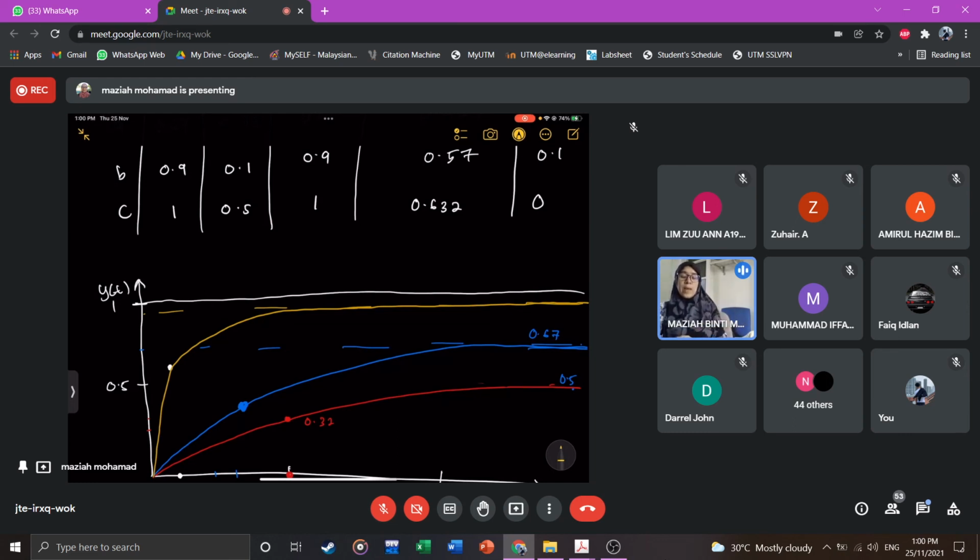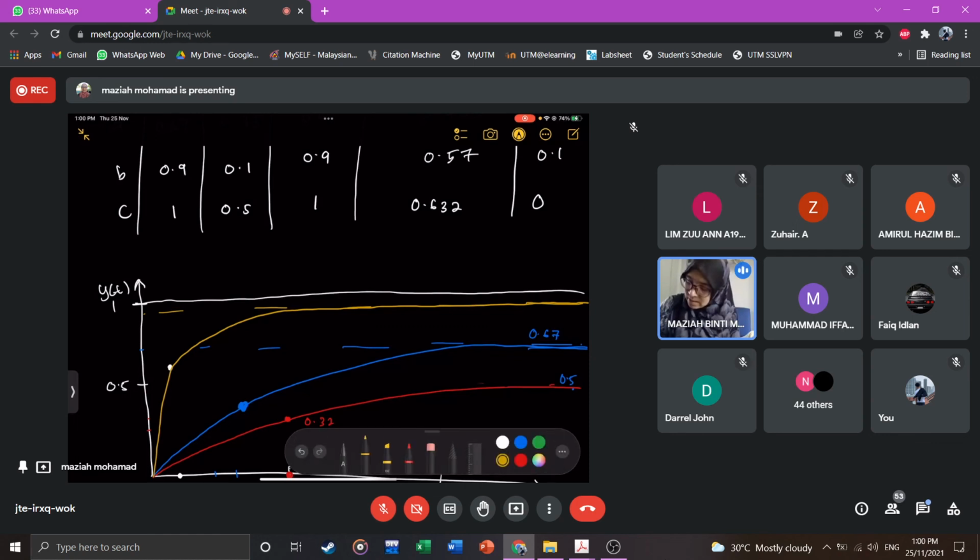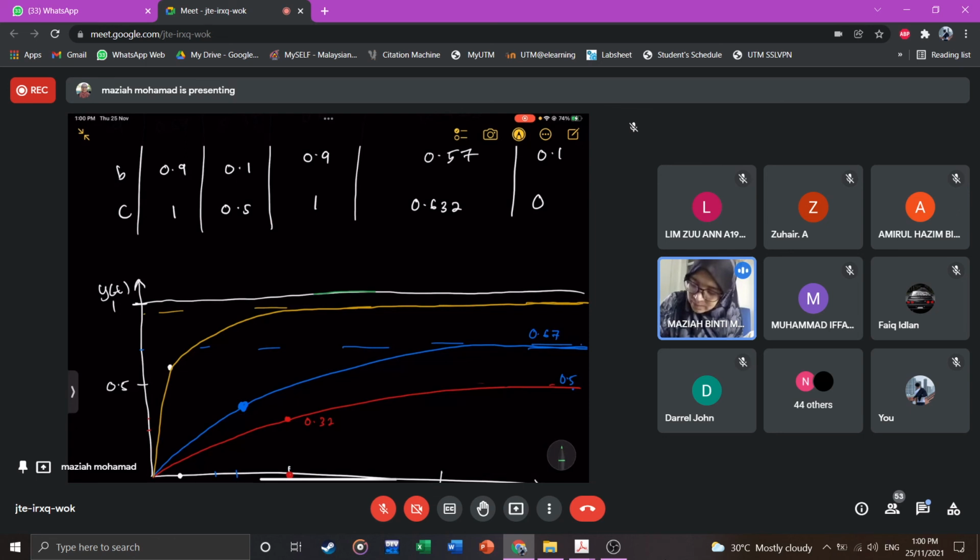So we're going to compare the response when we add a PI controller. PI controller is for C. It will be reaching 1, and the time constant is 0.5. So it should reach 0.632. So 0.632 is around here, a little below 0.67.